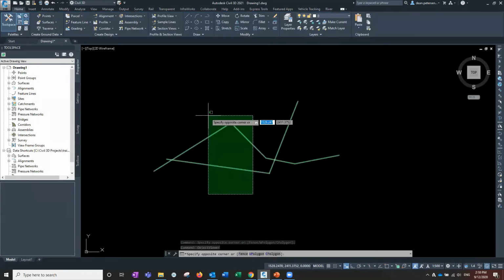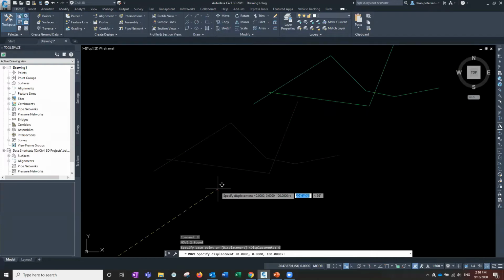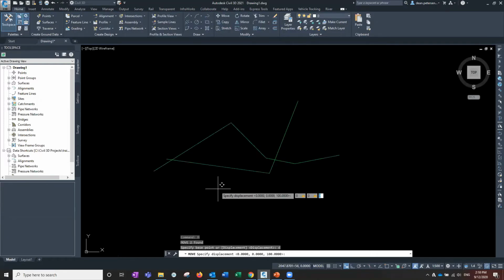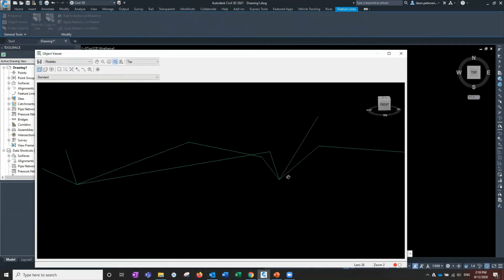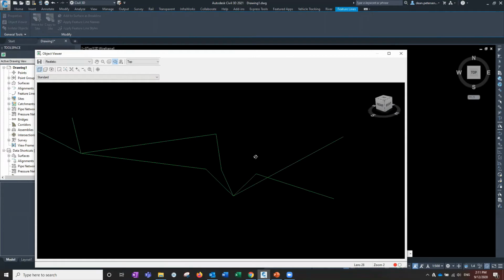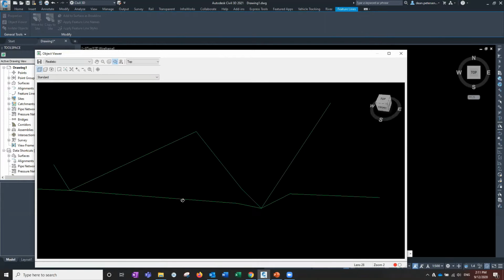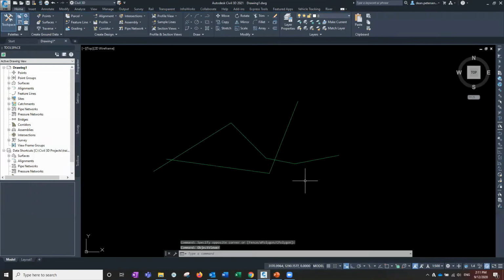So if I actually grab both of those and do a move command of, say, 200 on those, 0, 0, 200, it will have moved the other parts, but these ones all stayed at that initial 0 point that they were set to. So they actually become fixed points rather than movable. If you move both feature lines, the actual crossing points stay fixed. So little command there, might find it useful at times, probably not for everything.